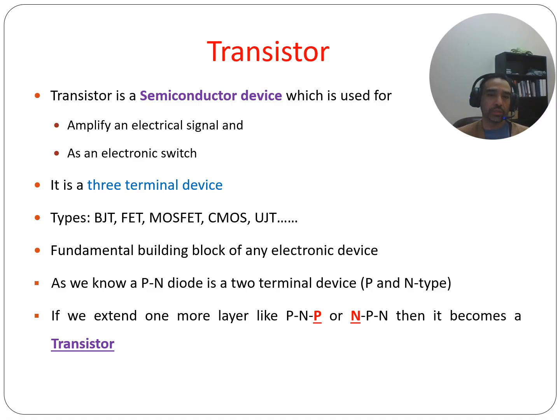The next one on the list is the field effect transistor. So what is this? It's a type of transistor that controls current using electric fields. So how does this work? It also has three terminals, but we call these a gate, a drain, and a source. And those operate by applying voltage to the gate to control the current flowing between the drain and the source. A key feature for the FET is that it uses an electric field to control the flow of current, and that makes it efficient for certain types of applications.